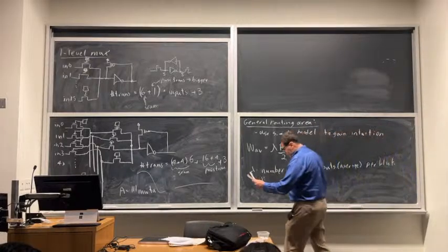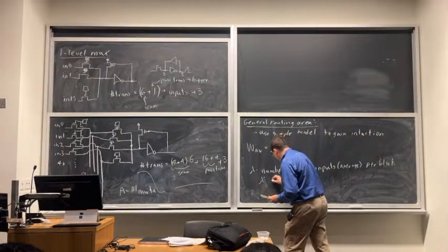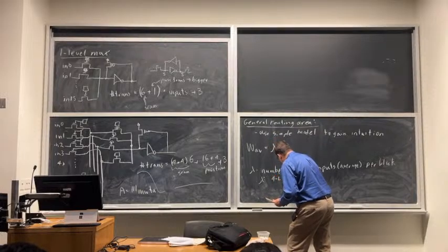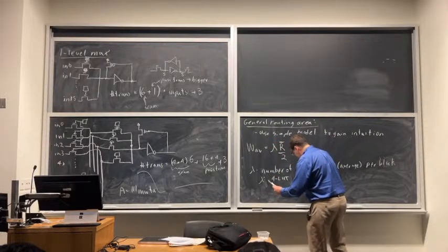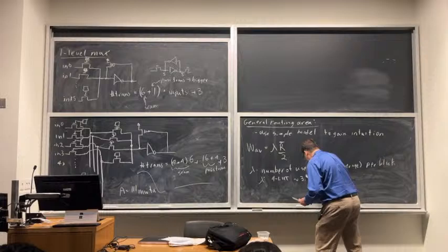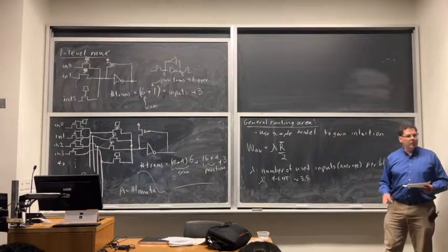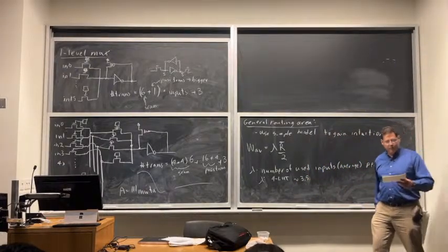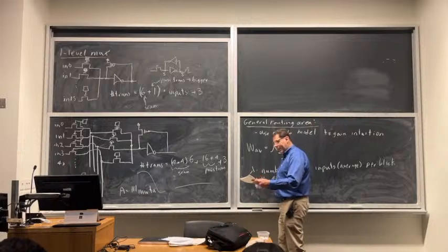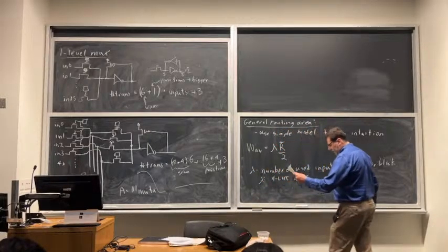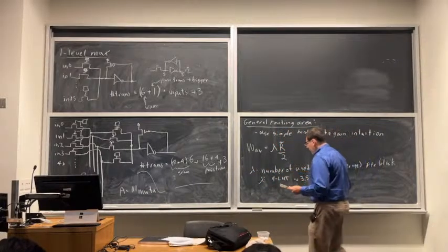But a good estimate would be, lambda for a 4-LUT, probably about 3.5. Okay? So I'm going to use that. So close to 4, but not perfect, because there's parts where you can't use the LUT to its full potential. Okay, so what are the other things here?